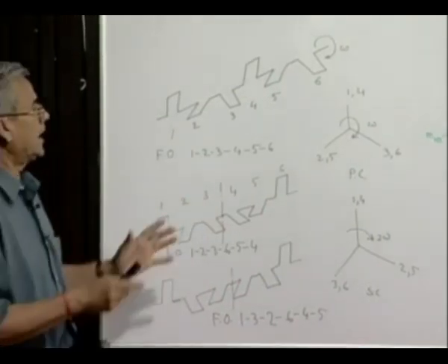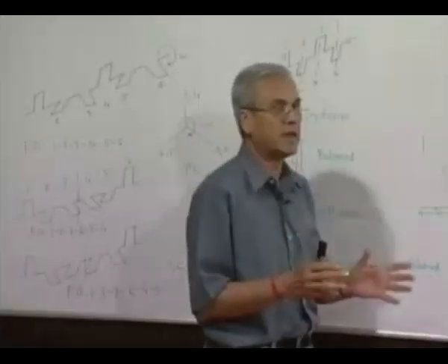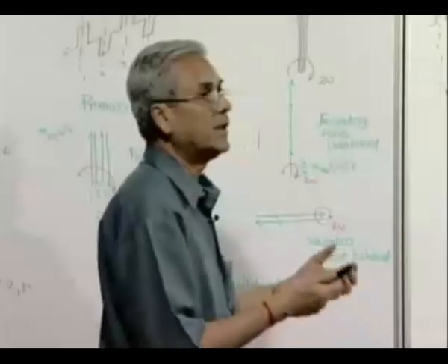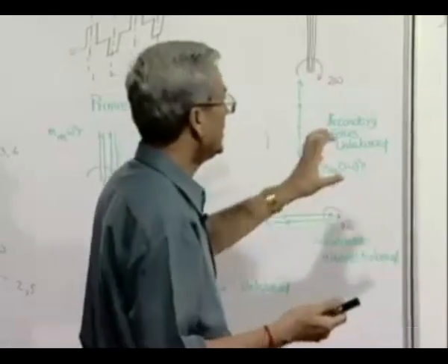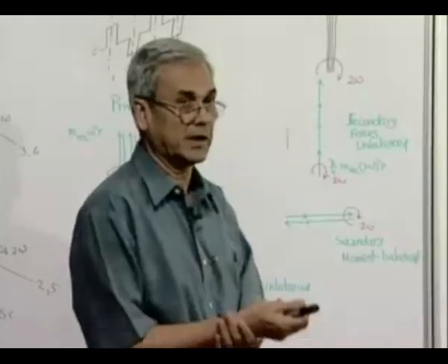Thus, the arrangement of the same engine, if properly designed, can be completely balanced without taking the trouble of attaching active measures like putting separate balancing masses. The unbalanced forces themselves will neutralize with each other.